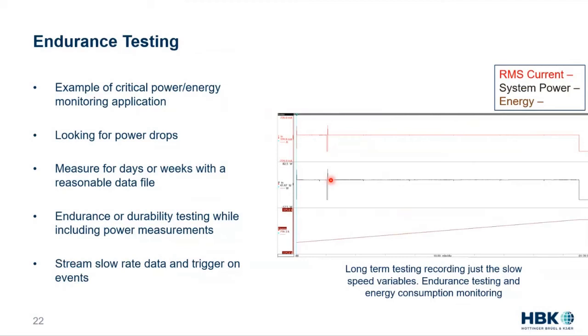But then if an event happens, you can have a trigger and take that very high-speed data, that 2 megasample data, and have a buffer where you can know 10 minutes before my failure, 10 minutes after my failure, or you could just have a slow stream of data and understand a 10-week test, a 10-hour test in its entirety. So nothing too exciting, but these long endurance tests, having a proper amount of data, and understanding failures and having data for failures can be very important.